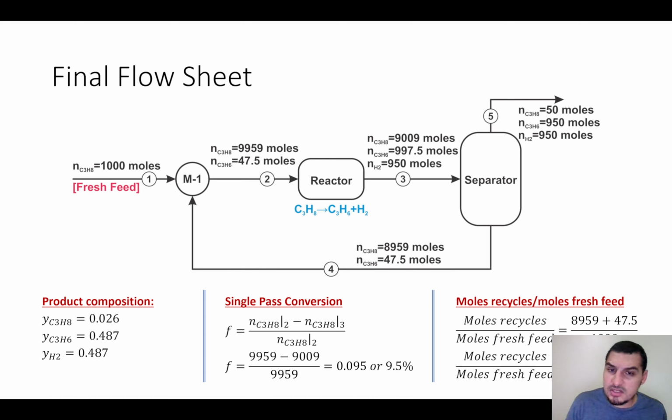And this is something that you can try yourself. For example, let's say that you have the same problem and you solve it with different givens. You put the reactor conversion, make it 50%, for example, and then calculate the flow rate of the recycle stream, and keep everything the same. The relations between the separator streams are the same. The only difference is that the given information that you know is the conversion in the reactor, not the overall conversion.